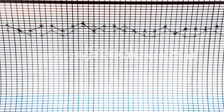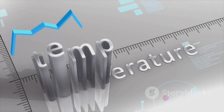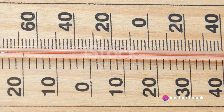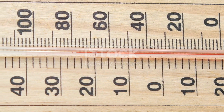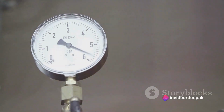Now, imagine the chart. Picture a two-dimensional graph where each point represents a specific condition of moist air. The horizontal axis measures the dry bulb temperature, the air temperature measured by a thermometer freely exposed to the air but shielded from radiation and moisture. The vertical axis, on the other hand, measures the amount of moisture in the air, or humidity. Between these two axes, a series of lines represent other critical properties.